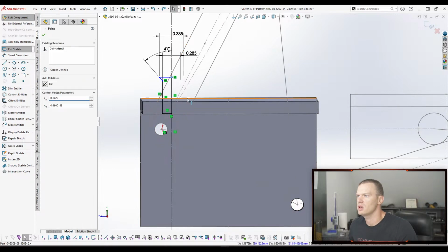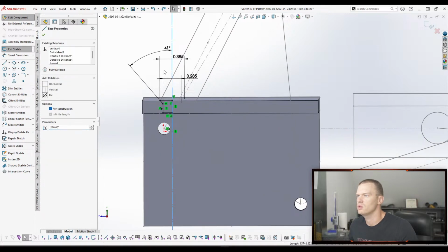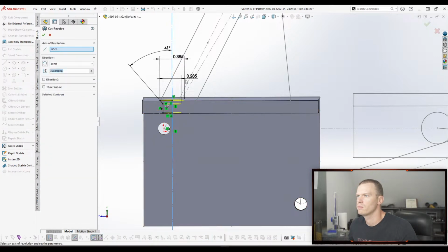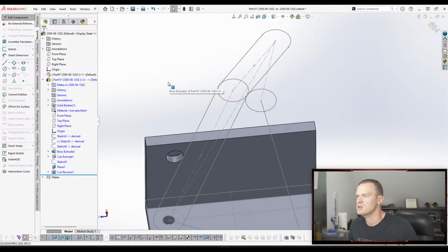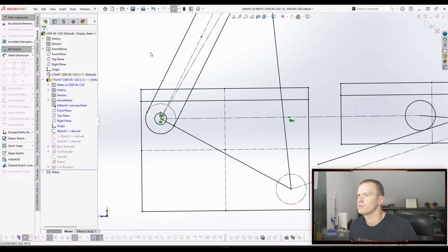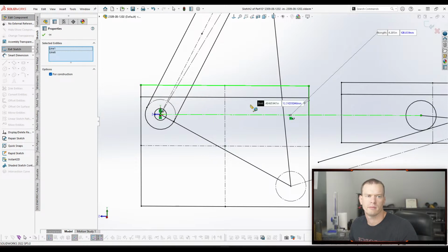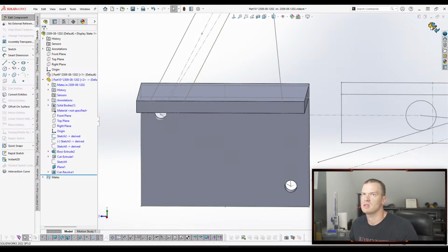So we're gonna locate like this for now. And then we'll do the revolved cut. Yeah, looks like something's not quite right with maybe the way that this sketch got brought in. Should be parallel. The question is, are these two parallel, I guess? They are. So we'll go back to this base sketch and see what's up.